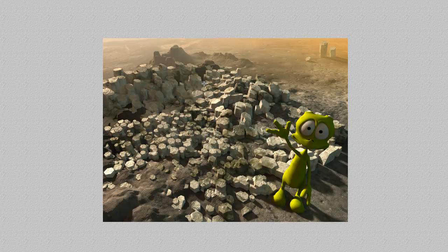But when you change to a matte material, and I'm looking at this area in particular, then the more complex lighting provided by ambient light here really shows up the geometry. You have the subtle shadow regions and quite subtle lighting. No direct lighting is arriving, the sun's skimming over the top of that portion. So for matte materials and complex geometries, think in terms of using true ambient light to get the best out of your scene.